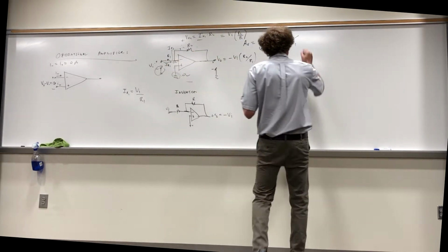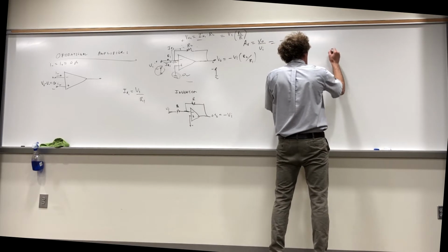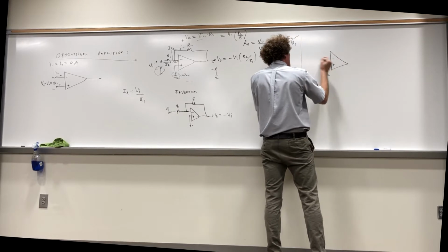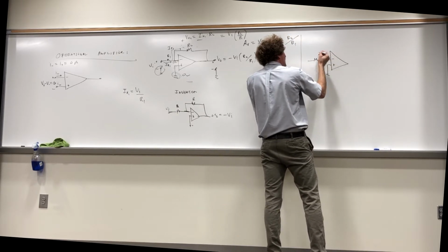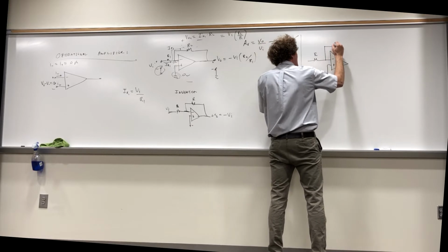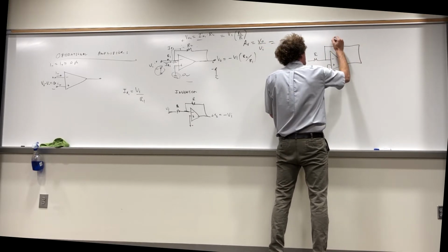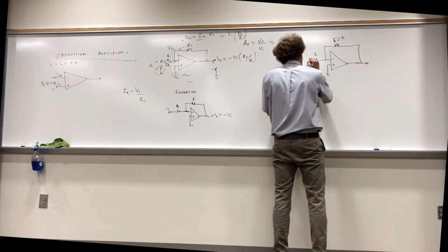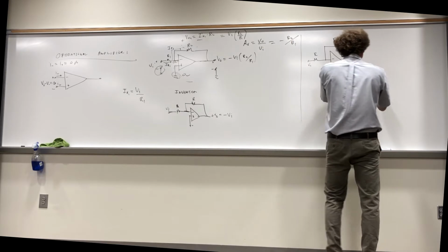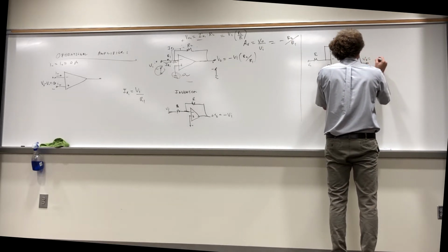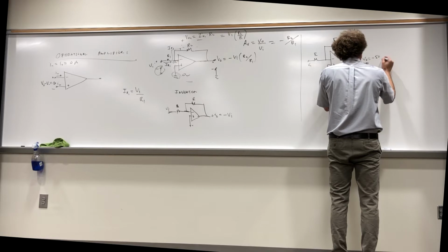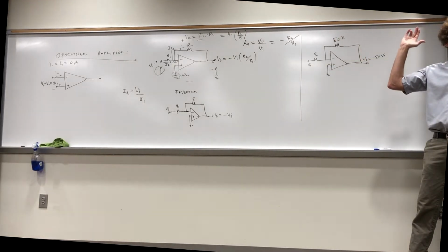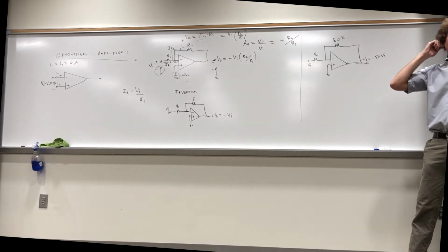Most of you probably see this. Well, I would just start and say this. I'm going to take one operational amplifier here. I'm going to put a resistor here. I'm just going to make this R, whatever it is, make this 10 R, or 50 R, if I want to gain a 50 R. Now I know if this is V in, my V out here would be equal to minus 50 times V in. Do you agree with me, class? How many see this? Everybody with me? Now, I don't want that. I want a positive value.